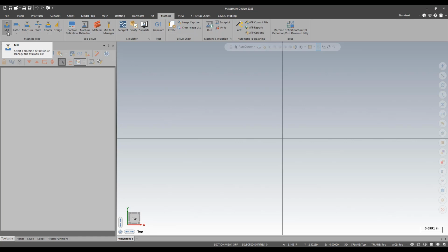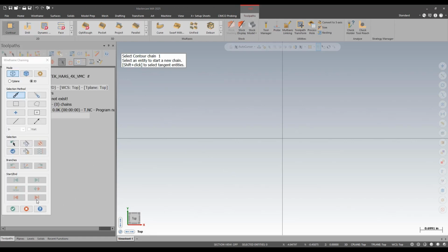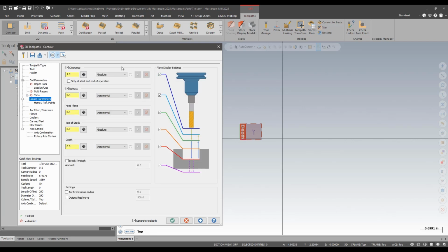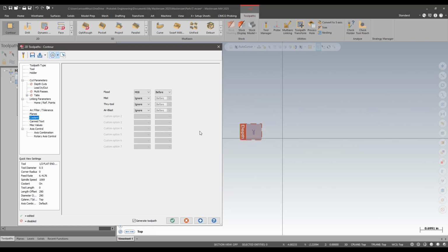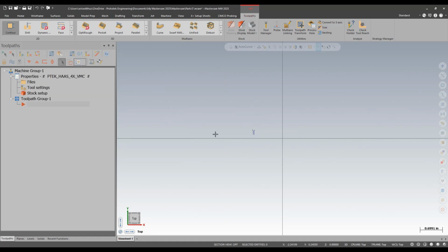Also, you are now on a network share, so that includes things like your toolpath defaults. So whenever you create a toolpath, you have certain settings, like maybe you have it set to where comp or absolute on your linking page, or whatever settings you want. And if users don't agree on these settings, you don't want to just hit the save to defaults button anymore. When you hit that, you are now setting it for every user on the network. So when you hit that save button, it's actually going to a specific file, and that is set by your post. And everybody is now sharing posts, so you can't really customize it there either.